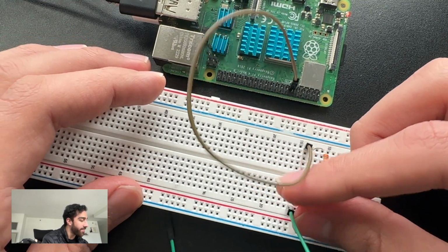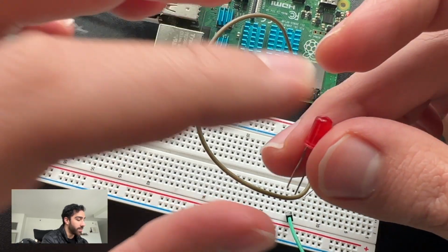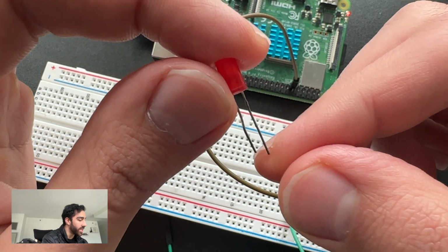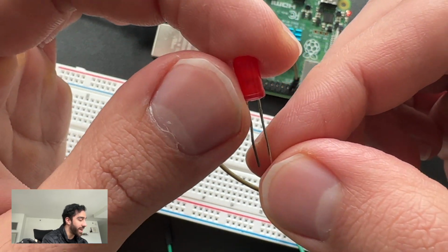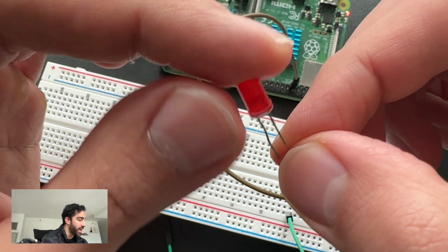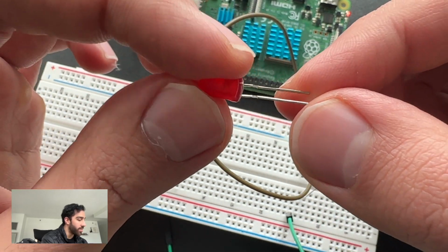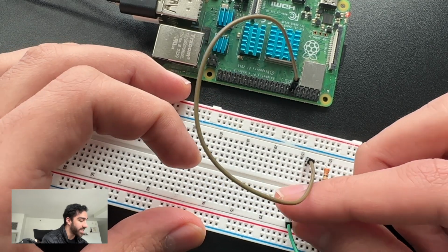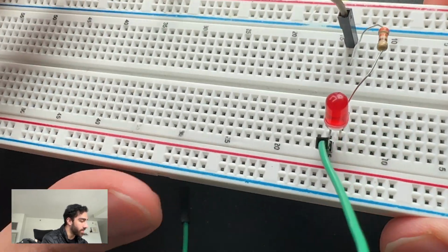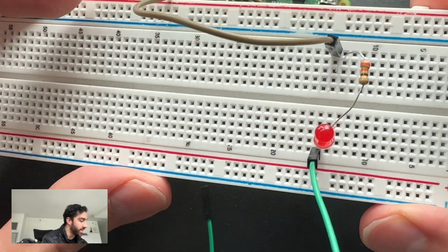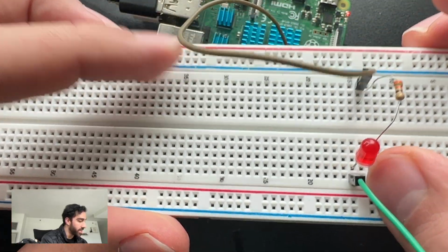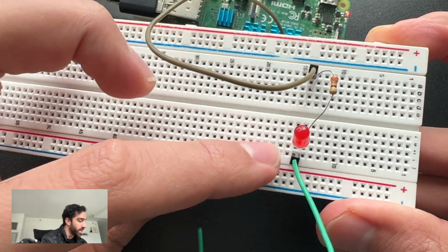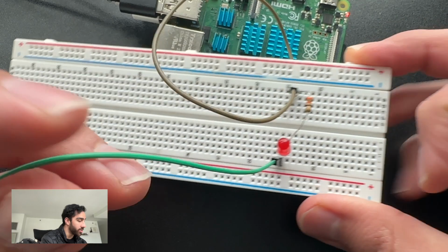And then here we have this LED. This LED is very common. It's just a 2-node LED. One node takes power. The longer side is what receives power, and the shorter side is what goes to ground. And then each end goes on a separate row on the breadboard. The longer end attaches to the resistor. So you see that the longer end is on the same row as the resistor, and then the shorter end is connected to row 15, and then it has another male to female jumper wire.